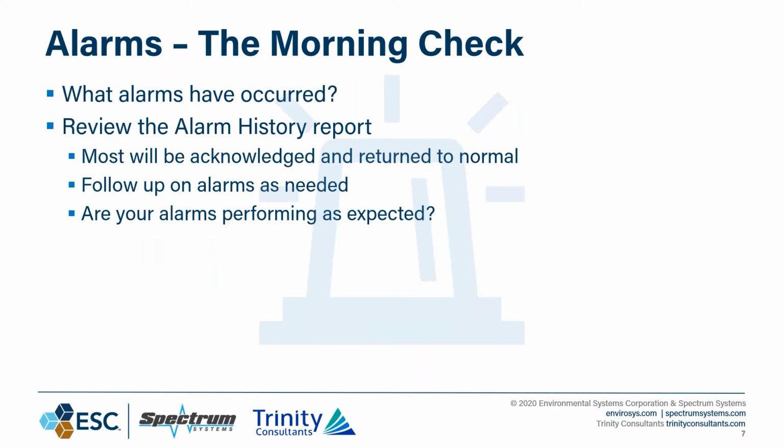So let's start with our alarms. And this is the morning check. What alarms have occurred? Are they informational? Are they crucial? Are they just a nuisance? They need to be reprogrammed. We had talked previously that important alarms should probably be latched, meaning that they stay on screen even after they're acknowledged until a situation is corrected.